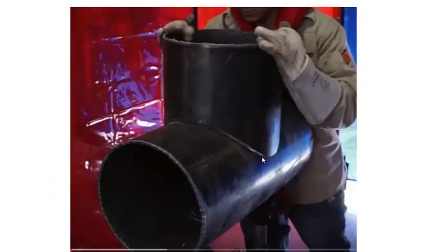I don't really want to go to that one. Let's go to this one. That's what this guy's done here. He's only done the cutout on the branch, and then he's dropped it against. This hasn't been cut out on the inside yet, and that's a realistic way to do this. You can develop and work off of the branch. Once you have your branch cut the way you want it, you can just drop that against a header to use that as your template for the header cutouts. And so that's kind of an easy, common sense way. Develop your branch, use it to lay out your header. And you know, if I was building my own stuff, I'd probably do that like all the time. And that's what they'll have you even do on like piping branch tests.